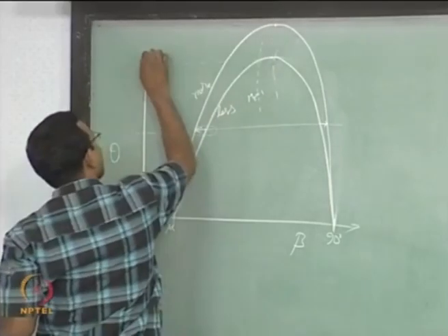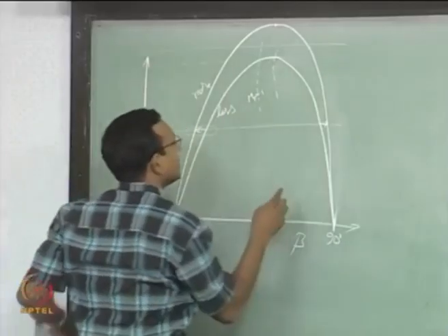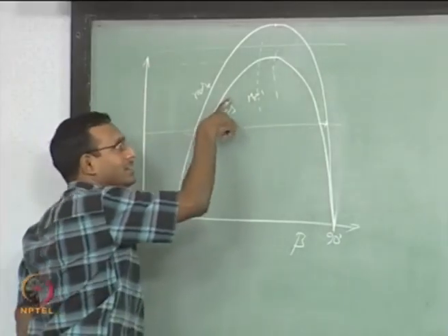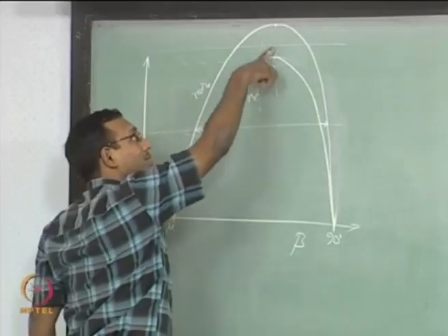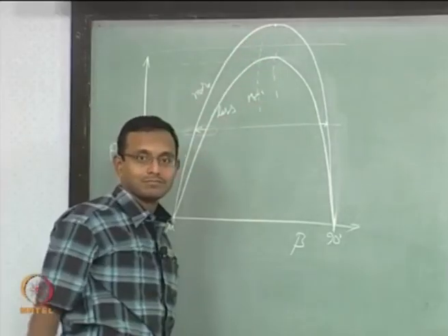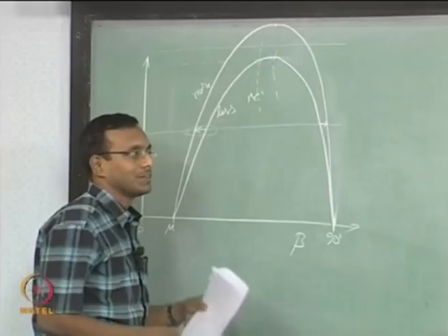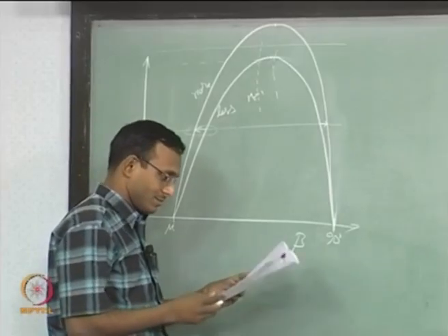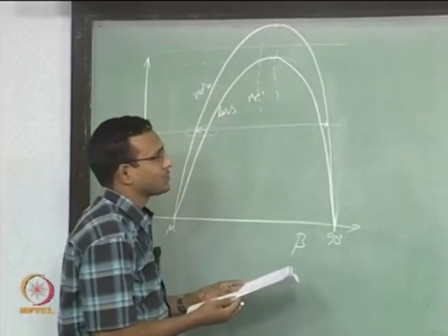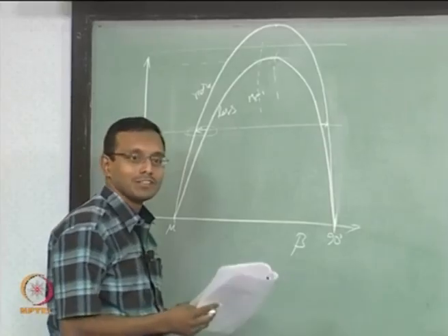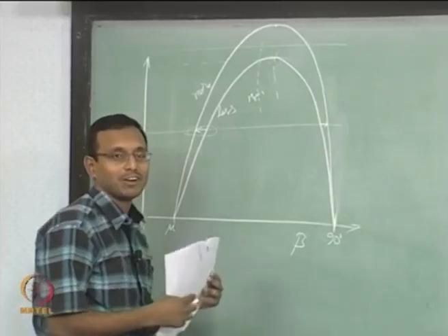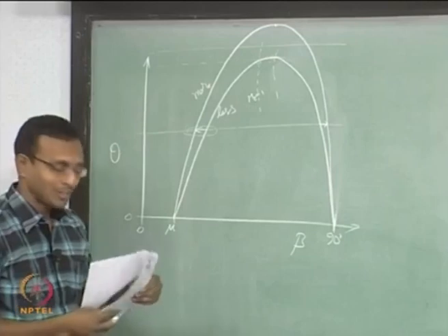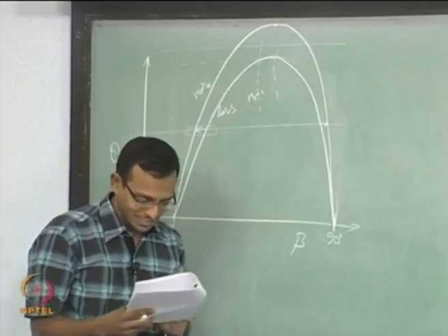If I had a case where my theta was this, if my gamma was higher, it will have a detached shock, if the gamma is lower, I will have an attached shock. This is related to compressibility, okay. So do we have a solution for solving flow behind a normal bow shock yet? Not really, okay. We cannot solve it for a bow shock, we will just leave it like this.